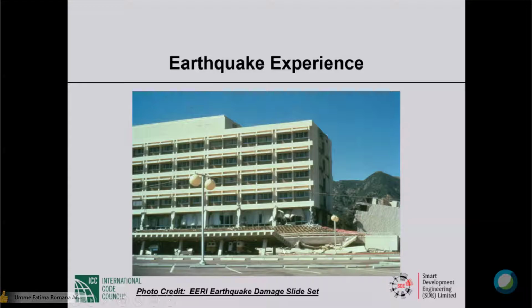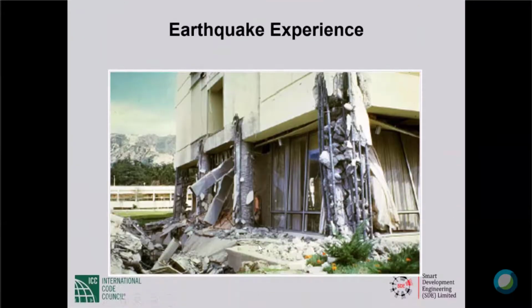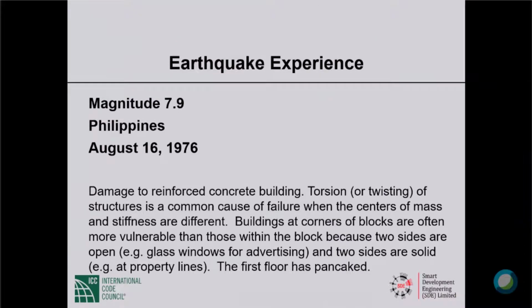Anyway, the canopy has not entirely collapsed, but some of the columns have collapsed. So the ambulances underneath are pinned there. They cannot move. They are stuck. And when ambulances don't function, a hospital cannot do much business. So the hospital itself is standing up, and standing up because of the factor that I mentioned already. But this very fact that the cantilever column system failed made the hospital non-functional. This picture I have gone through, so let me not spend more time.